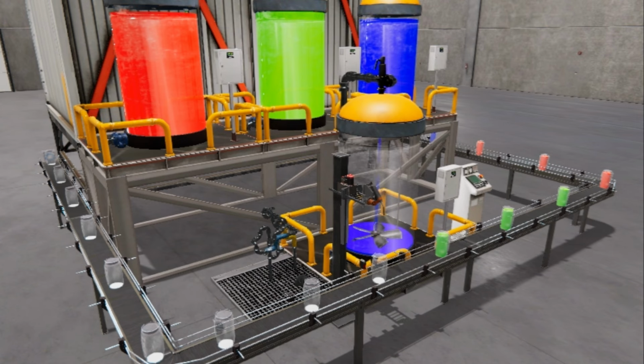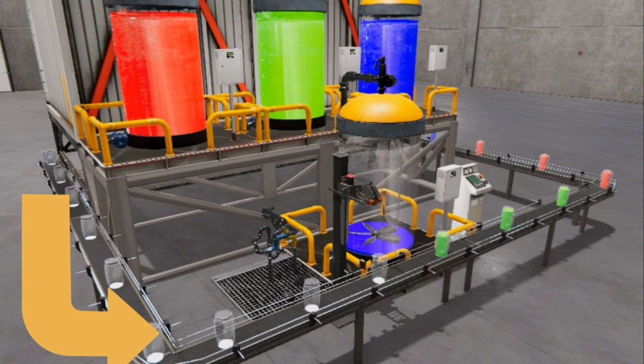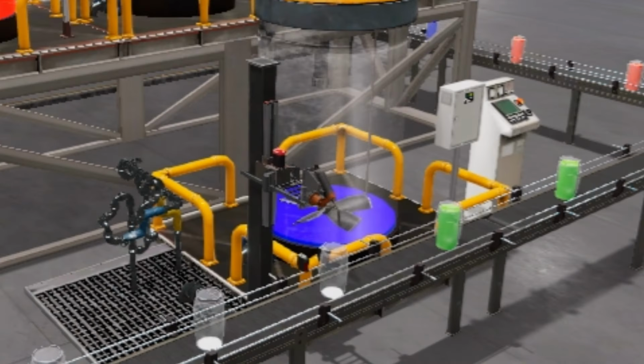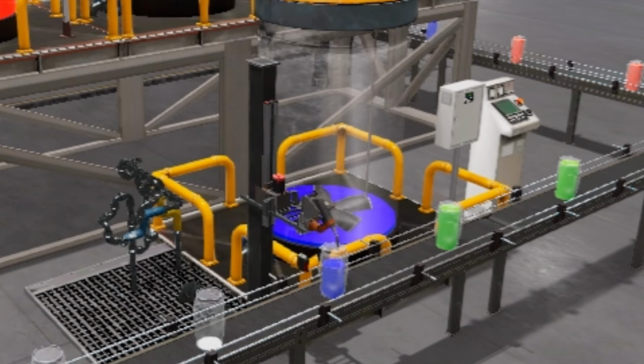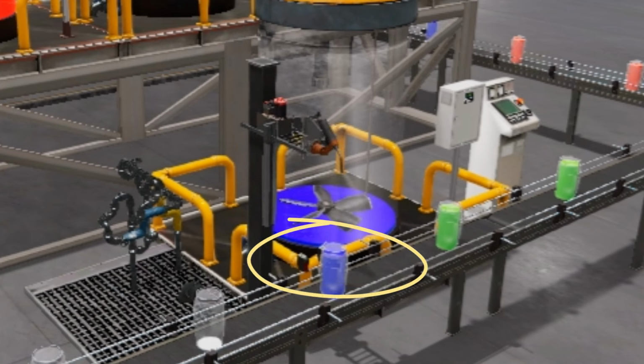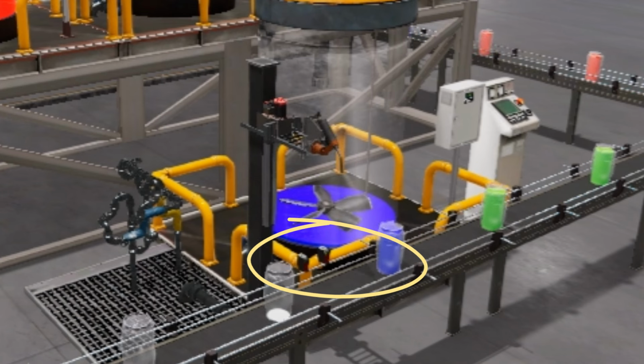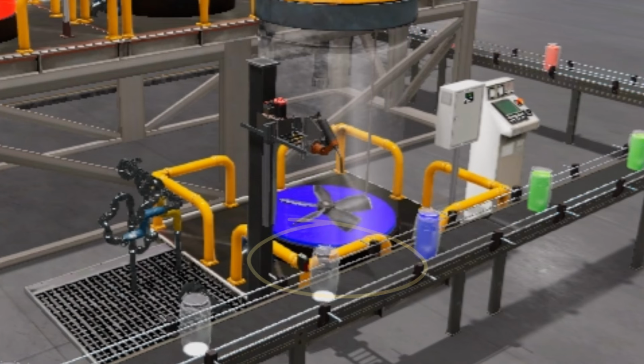When the work part creator is turned on, bottles will move along the conveyor line. They will move along until the first and second photocell detects the bottle. This will stop the work part creator. To achieve a more accurate stop location for the bottle, the conveyor's slow output will be turned on when the first photocell is seen and turned off when the second photocell detects the bottle.